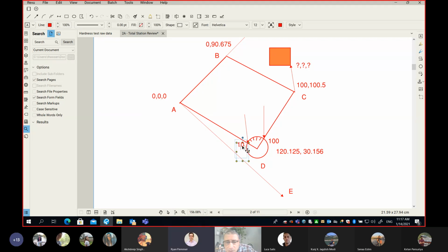It has no meaning. There's no reference to it. You need another number to reference it off of. I would agree. 10 has no meaning because simply 10 is relative to the 0. Let's say somewhere here is the 0 of your compass. So that's the 0, and simply your 10 is relative to the 0. And the 0 is oriented anywhere on site because I have done no effort. I got it from the box, I level it, center it, I take one reading, 10, and it has no meaning.